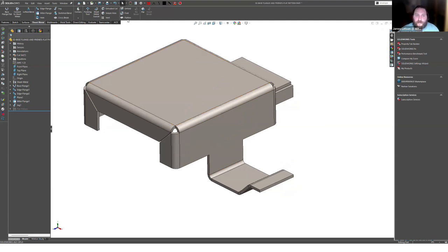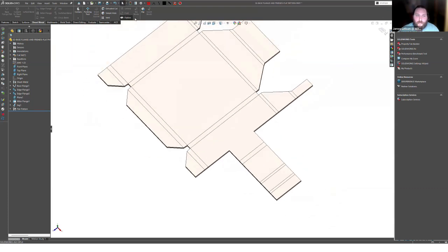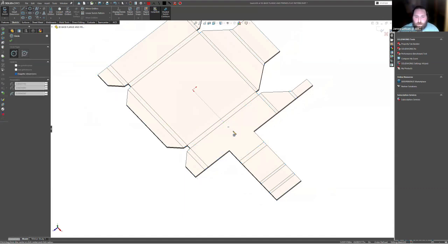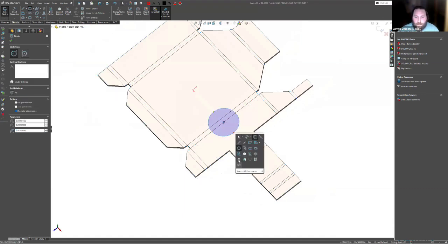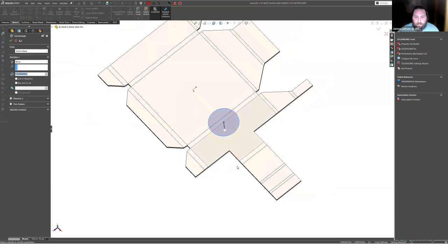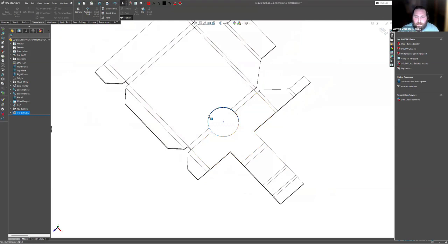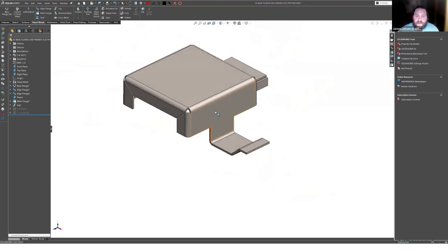And I've seen people do it a lot, and then it ends up causing them headache in the future. Well, they'll hit that flatten button up there. They'll then come into a sketch, draw their circle, and cut it. Okay, so now you have that circle that follows the profile on both of these faces, right? But when you come back up here to flatten, you can see that it now suppresses.